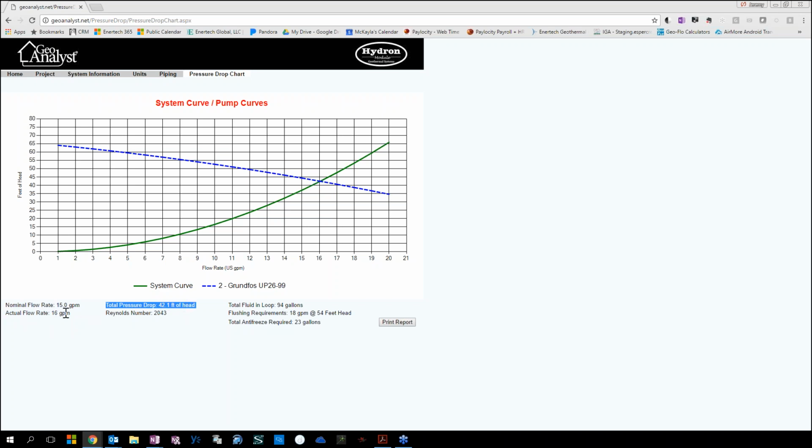So what we're seeing here, just for anyone who may not recall or doesn't know, when you're sizing a pump, what you need to know is how big is the pipe, how far am I going to carry this water, how many gallons do I need to carry, and how thick is it?